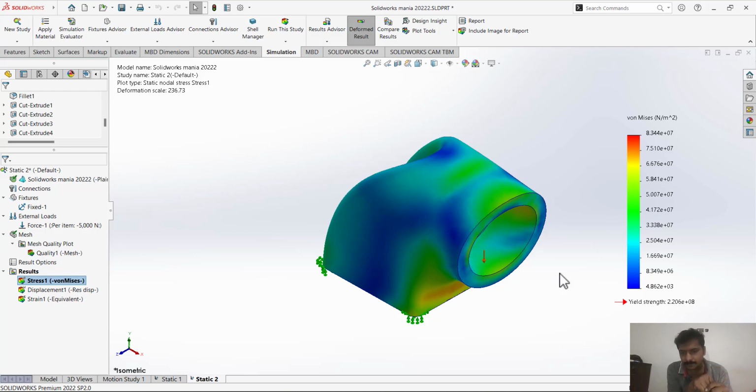For this case, we selected plain carbon steel. If we are able to select a less costly material that fulfills our functional requirement, we can run this static stress simulation and see if the cheap material is okay with the applied load. So we can make the decision according to this result.